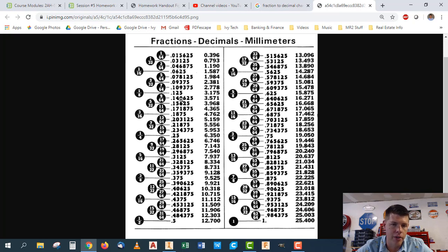But if you look at our drawing, there's all kinds of stuff that they've rounded off on eighths. Like this, they would round off to 0.13. This would round off to 0.38. And I told you 7/8 rounds off to 0.88. Most designers have used these enough where they've at least memorized the 8ths and 16ths, if not the 32nds. Memorizing at least the outside of this chart will make your life a lot easier if you're working in inches. If you understand the 16ths and 8ths, when you see a number, you immediately know what it is, just through repetition.